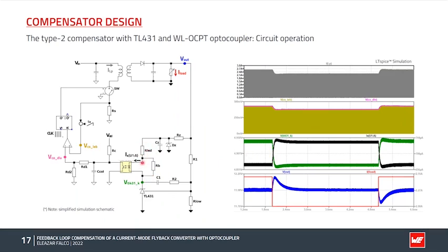Higher LED current will cause a higher collector current of the optocoupler phototransistor because they are just related by the CTR of the optocoupler, a gain term. So we have higher collector current flowing across the collector resistor RC.